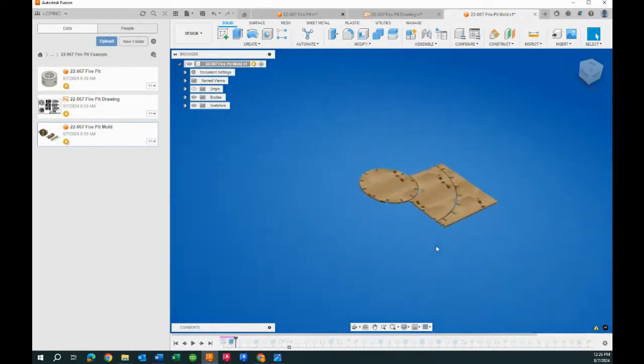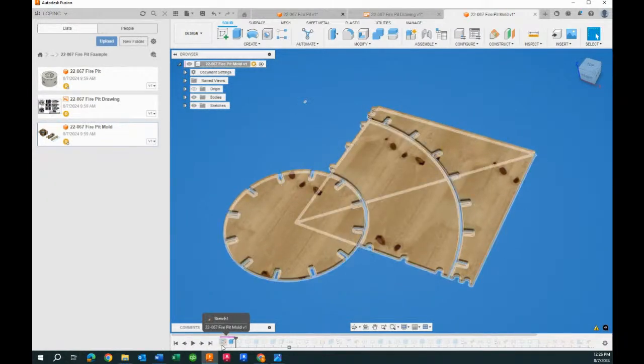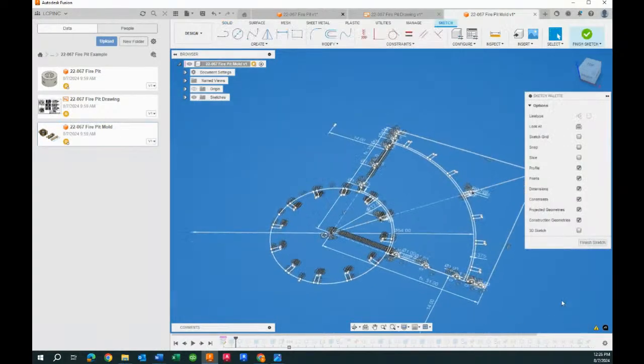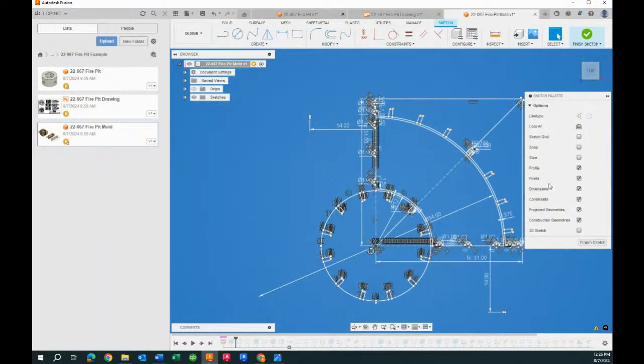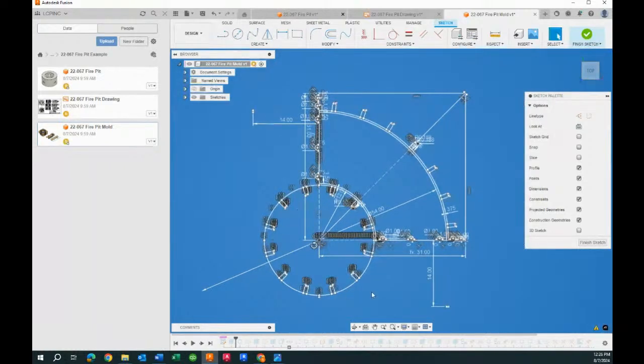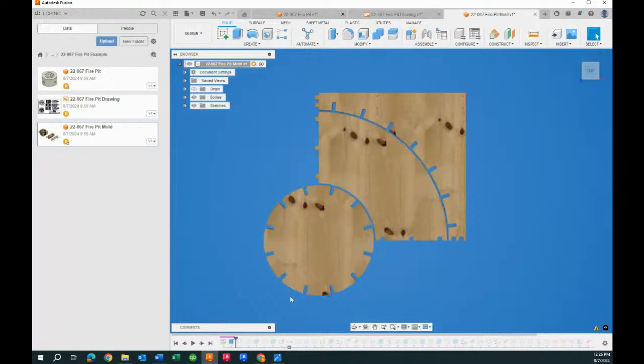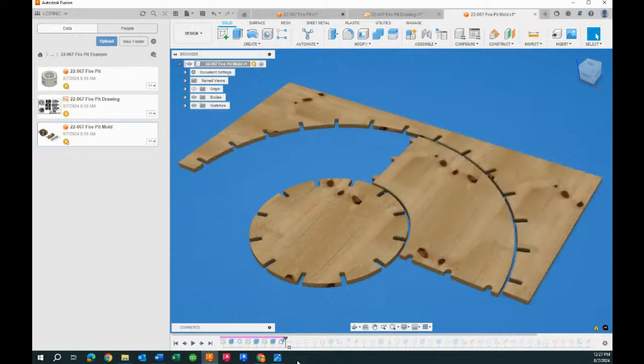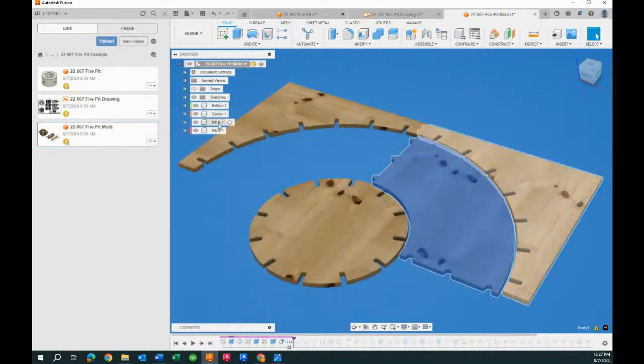So going back through this, the first part is how do you integrate this into formwork? It gets back to the 2D drawings. In this particular case, we did all the 2D drawing in Fusion 360 and laid out each component of how we wanted to see it, extruded it up, and from there we built out every individual component in the 3D model, if that makes sense. Once you create your models, where you have your bodies laid out individually, ideally you would label each one of these bodies: this is unit A, this is unit B, this is unit C, and then you would create components.